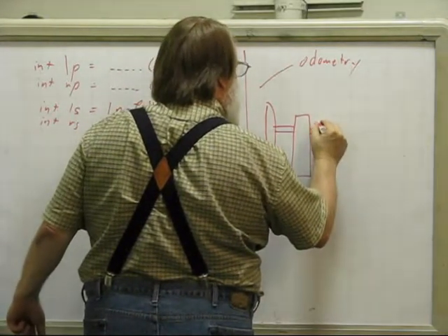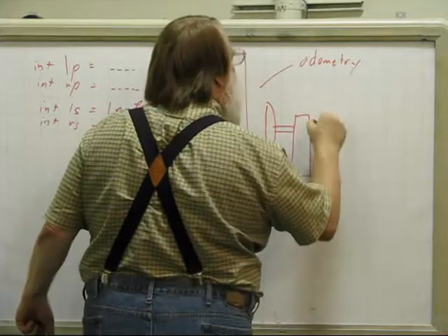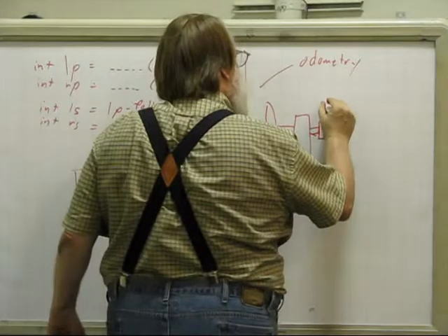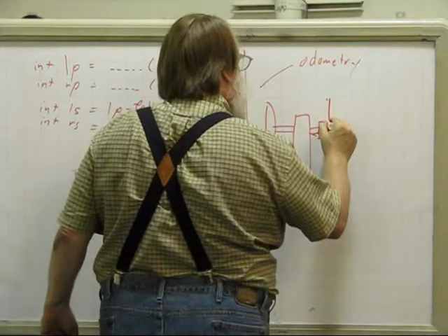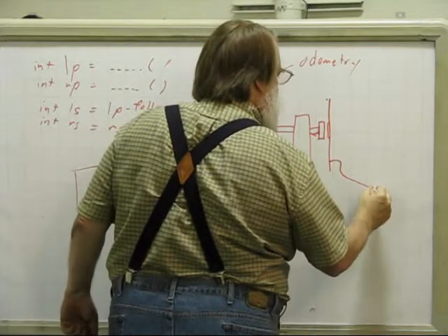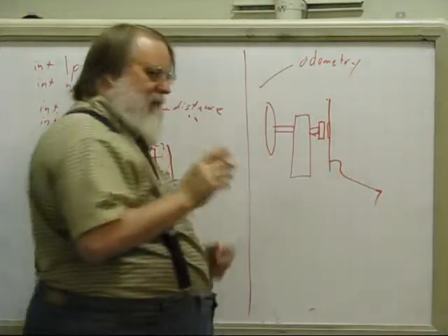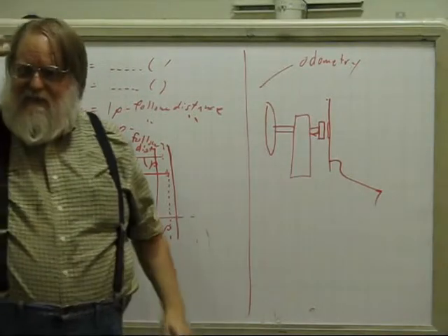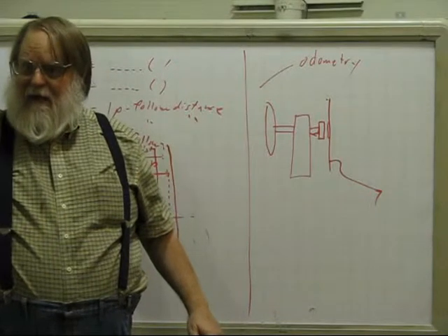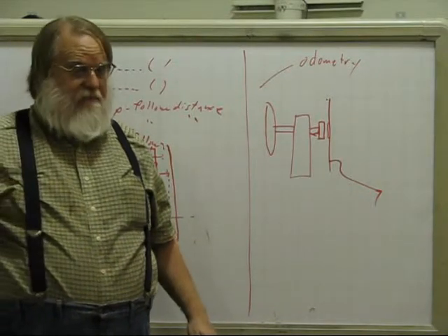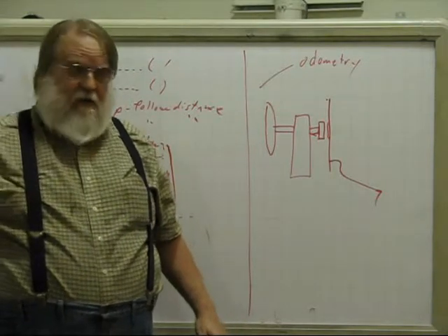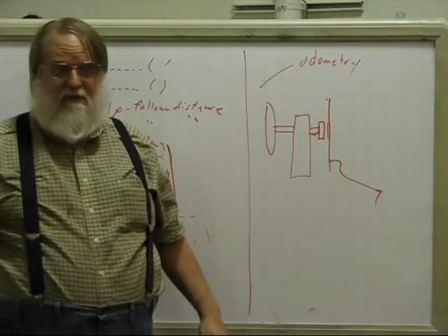What we do is we put a magnet on here. We have to mount that in a magnet board. And then there's going to be a printed circuit board that has a little chip on it. And then this wire goes up, and another wire going up. And what that board does is it senses the magnetic field of the magnet. And it can give us a very accurate positioning of the wheel. Okay, up to dividing 360 by 4,000. That's how accurate it is.